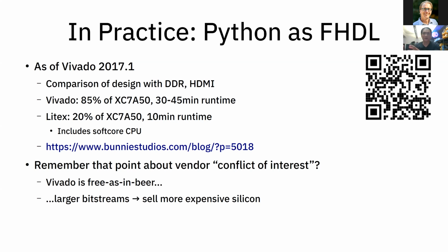They weren't optimized out, so it was carrying around large blocks of logic that wasn't even connected to anything. The good news is that for that particular piece of IP, it had generated intermediate VHDL files before going to these encrypted blocks that I couldn't do anything with. In the intermediate VHDL files, I could comment out the blocks, and then it would compile and run just fine.